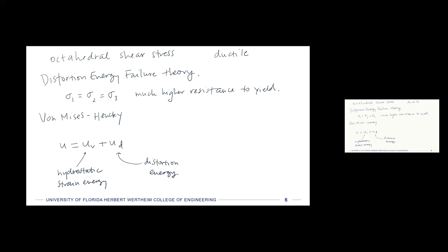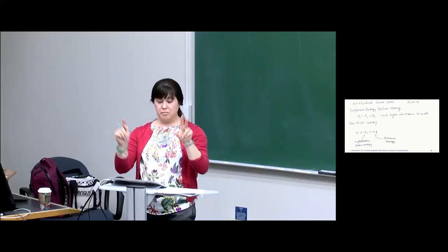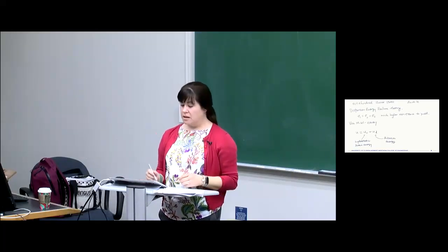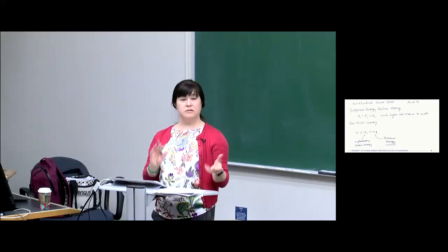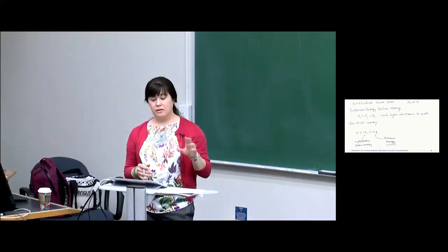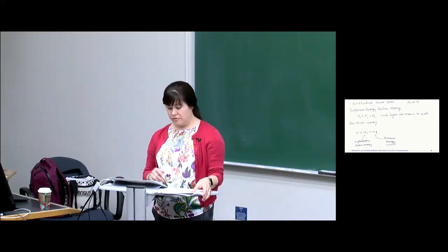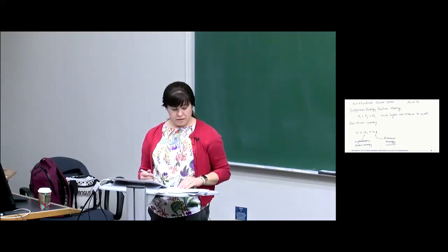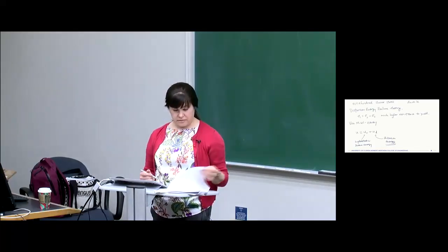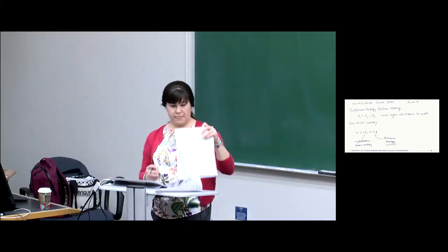And so if we have a stress state that's not a hydrostatic stress state, we can say that it is a hydrostatic stress state with another stress state superimposed on it. So that would be a stress state that only relates to the distortion energy. So it kind of allows you to get rid of the small changes from just the hydrostatic stresses. Okay.